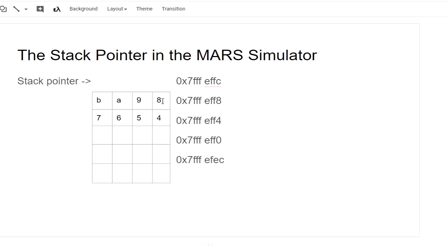If I want to store 2, I'll simply do stack minus 8, and I'll get down to EFF4. And then I'll write the first register that I want to use. I'll write its initial value in 4, 5, 6, and 7. In other words, EFF4, EFF5, EFF6, EFF7, because remember, it's a write word or a store word. And then I'll write the next one in this block.